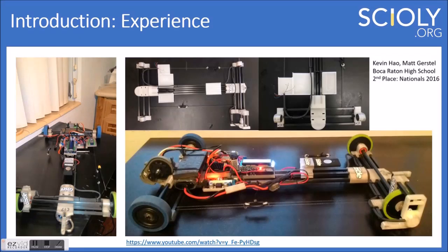The encoder we used had a high output, I feel like it was 12 or 14 bits of digital output, which is a lot of information to keep track of. So we really found the need to separate these functions to separate microcontrollers, just because we didn't have the processing speed on one. If we tried to run everything on one, it would start to miss clicks and stuff, and then we wouldn't have the right distances, which is a huge problem.